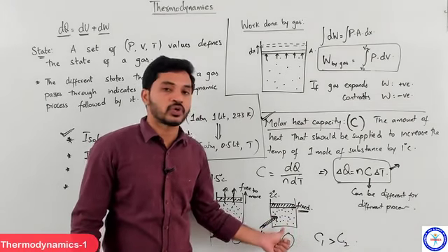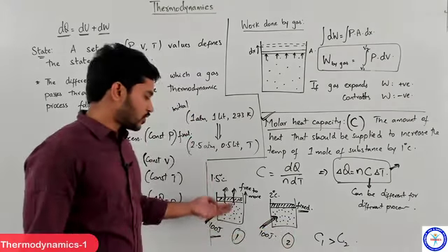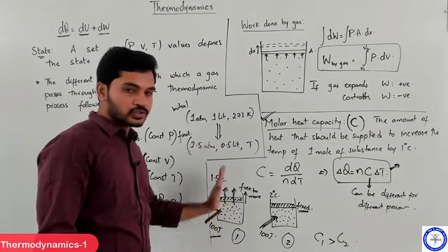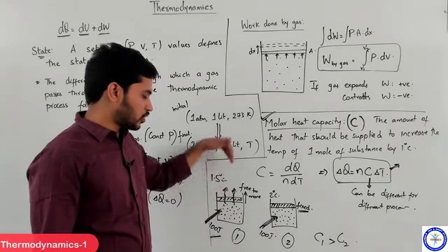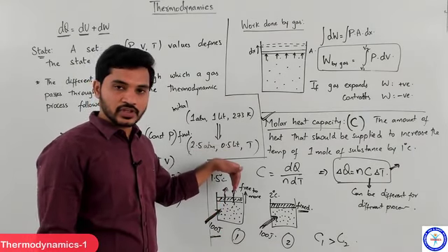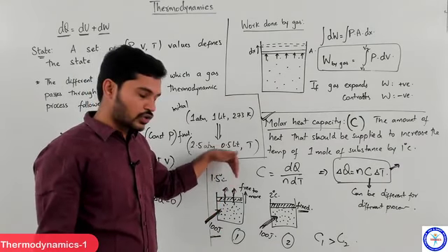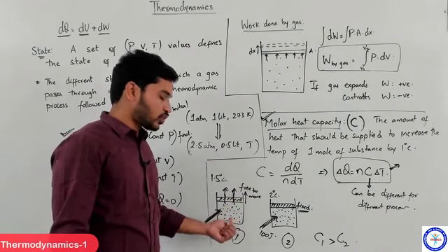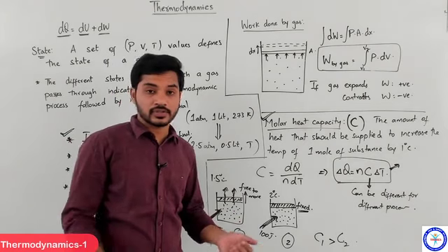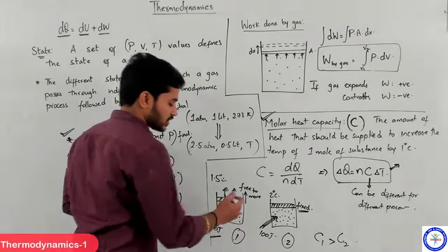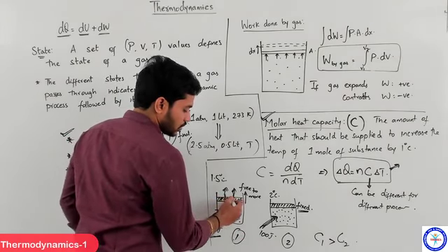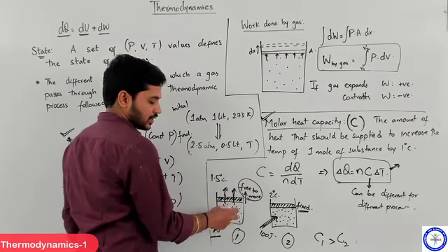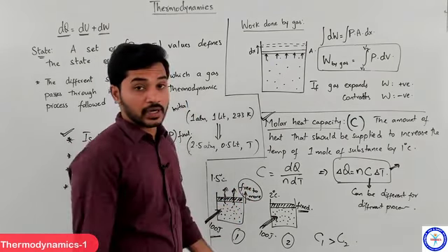And here the piston is free to move, which means outside force and inside force will always be the same, and because outside force is always the atmospheric pressure force, which is a constant, the inside force will also be constant. So this process is basically an isobaric process. So wherever we have pistons which are free to move, those will indicate the gas undergoing an isobaric process.